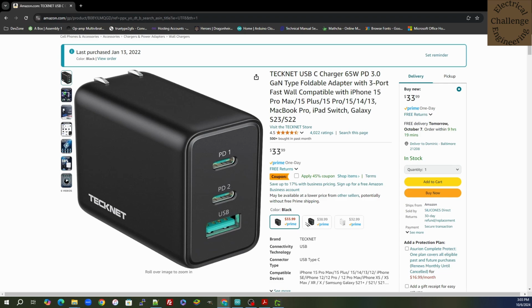So to harness the power of the USB-C brick, we do need to communicate with it. And like I said, there's a lot of people out there smarter than me that deal with this, so we're just going to use the chip. There's multiple ones out there. You don't have to specifically use this one. TI has one, the TPS5730, which is pretty reasonably priced and does what you need. I'm using the Diodes Inc. AP33772. Both of these are controllers that will do all the hard work for us. We just need to communicate over I2C to get it to do the work.